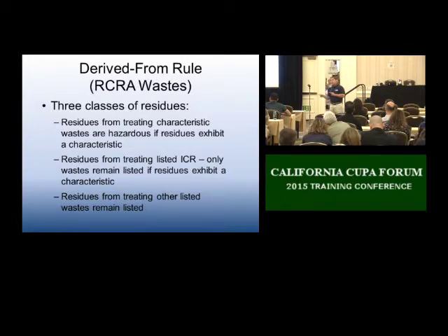You dilute it longer, you dissolve it longer, you digest it longer, you use a little more aggressive acid, and you only dilute it 10 to 1. Federally, you don't digest it as long, and you dilute it 20 to 1. So if you look at the criteria, federal and state, the state STLC, which is similar to the federal TCLP, for all the metals, they have the same threshold listed. But when you go to analyze a waste based on those concentrations of those chemical constituents, inorganics, in my waste stream, the methodologies are very different.